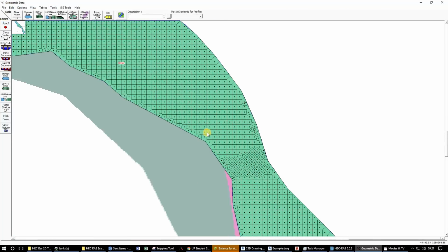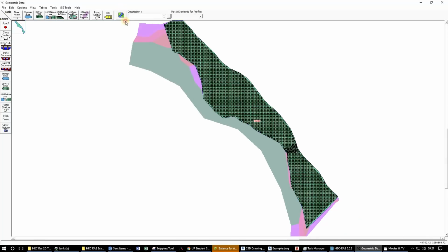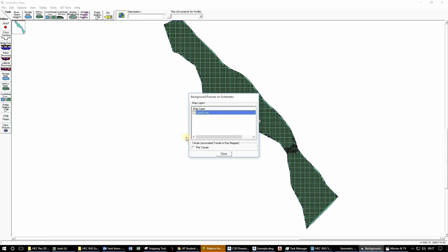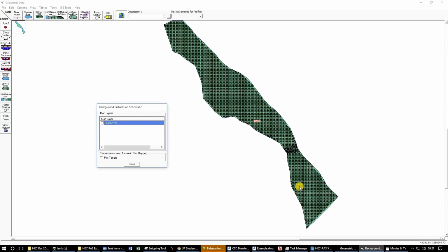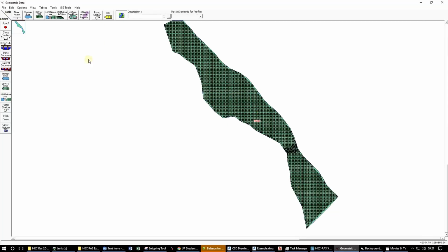That gives us the idea of that, and then we've got the mesh refined for now, and that's roughly how you can see that. Now next we will add basically the entry and exit locations, where the water will go into the 2D area and out of it. So we use 2D area boundary control links. You click on that, and where we want it from there to roughly there.